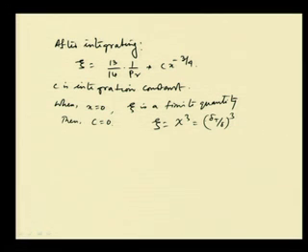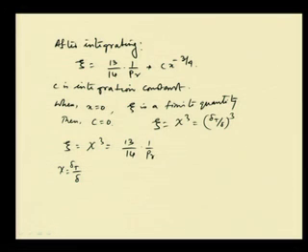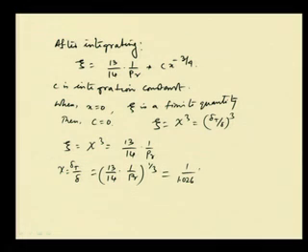That is from the logic, and then what we get is that zeta is equal to xi cube, and that is equal to 13 by 14 into 1 by Prandtl. So, then we can say that xi is equal to delta t by delta, which is the ratio of thermal boundary layer thickness to the hydrodynamic boundary layer thickness, and that is equal to 13 by 14 into 1 by Prandtl whole to the power 1/3, and that is actually equal to 1 by 1.026 Prandtl to the power minus 1/3. So, this is approximated as Prandtl to the power minus 1/3.